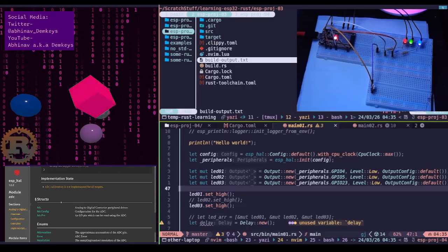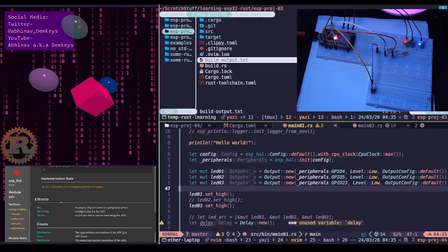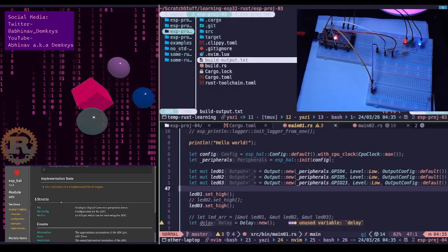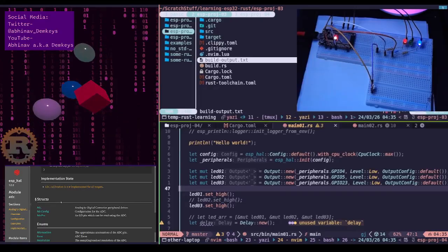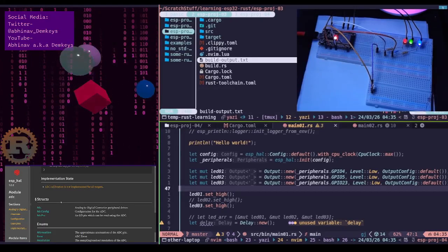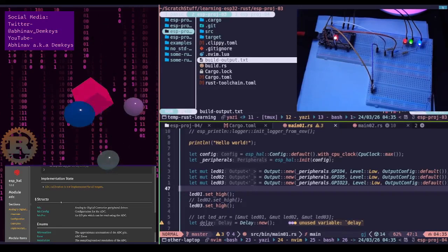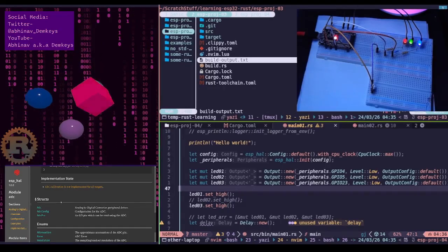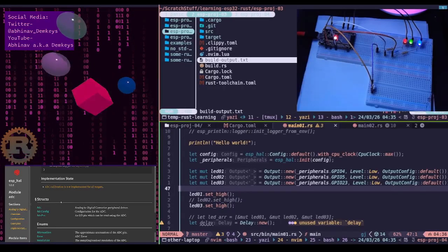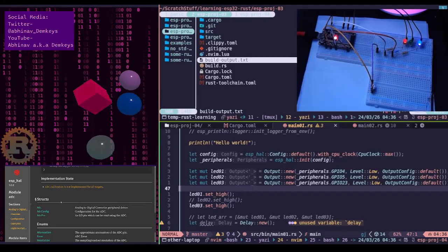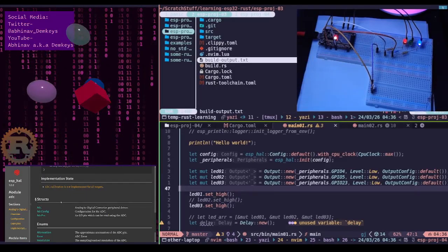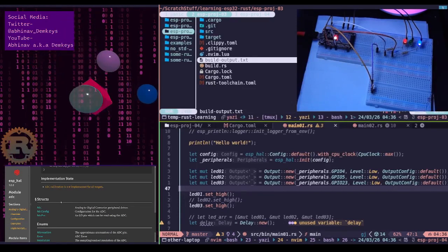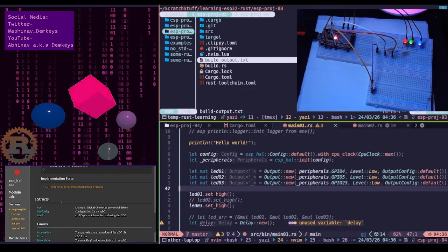So the current equals voltage divided by resistance. If you have a 10K pot on 3.3 volts, the current flowing through the pot itself is 3.3 volts divided by 10K, which is 0.33 milliamps. Wait, 0.33 milliamps.